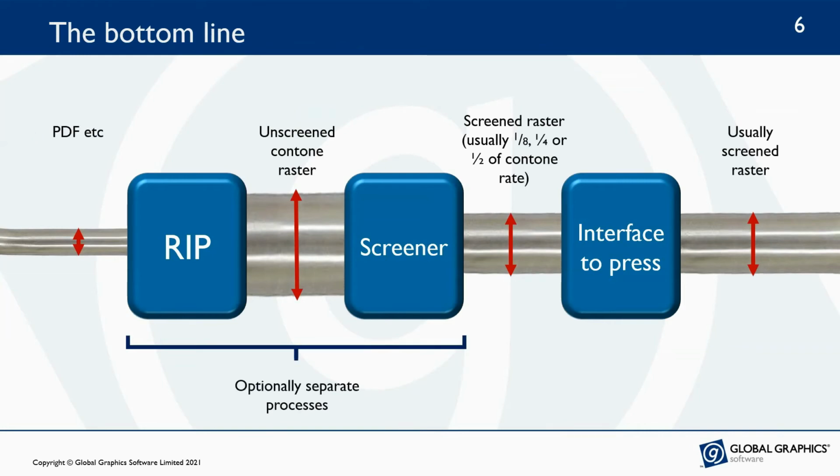The bottom line here is that you need to understand the amount of data that a digital press requires, its data rate, if you're building a DFE for it. Different stages in data handling will need different data rates. If you ever move unscreened data around, that will need the biggest pipe, but it's also the best indicator of the load on the RIP. And then you need to work out how to integrate an appropriate number of RIP cores to generate that much data without inflating the bill of materials with the DFE hardware.